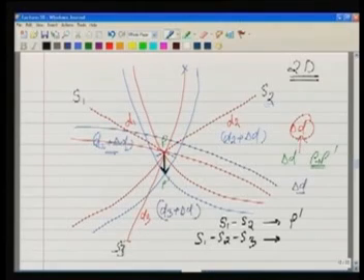No, because what we are getting as the position is now this triangle, which we call the triangle of error. That means our point has to be somewhere inside this triangle. Now if we observe this triangle, we will find the actual position is the centroid of this triangle.